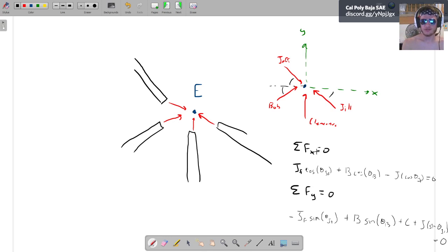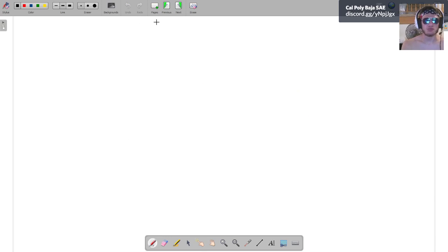So, while these are perfectly valid, perfectly good statics equations, later on, after we solve some other joints, they'll be useful. Right now, they're not very useful to us because we don't have any knowns currently. So right now, we have 1, 2, 3, 4 unknowns still. And that, frankly, doesn't do us much good. Later on, when we come back to this point, we'll be able to fill in all the unknowns, but for now, that is annoying. So, let's start at point D.